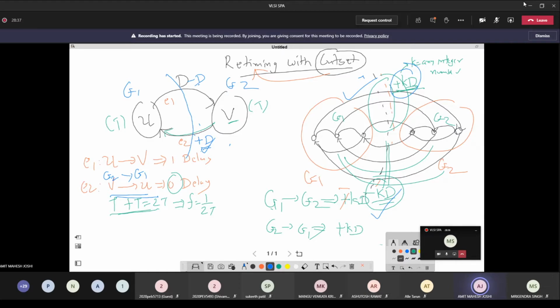So if I consider the retimed graph, then the retimed graph would be like this. U, V, here it is D, but here it has been removed. Now it is T. If you remember, yesterday through a retiming vector also we got the same solution. In order to break the critical path, we put D over here, but then it gets removed from my top edges.